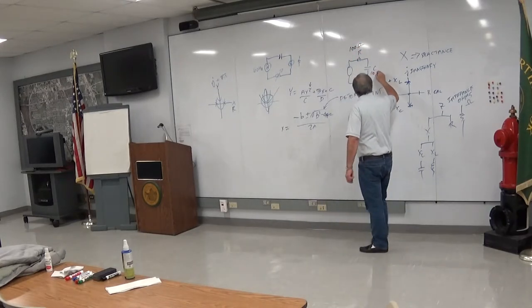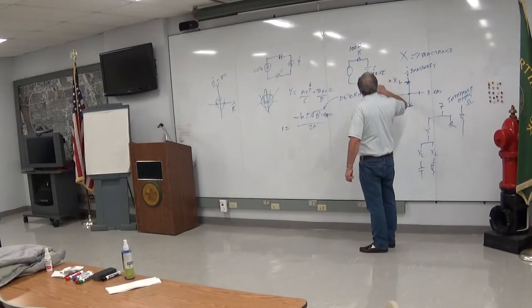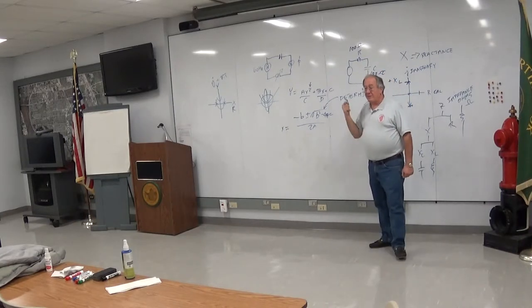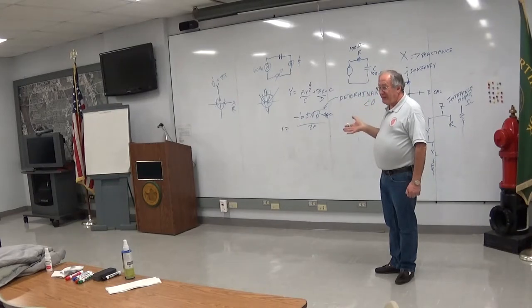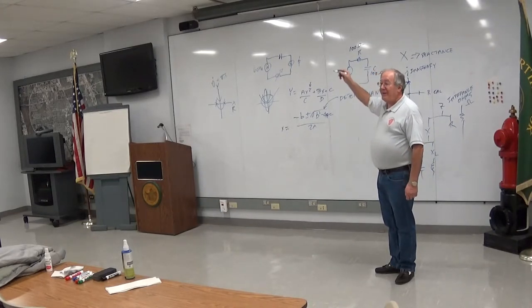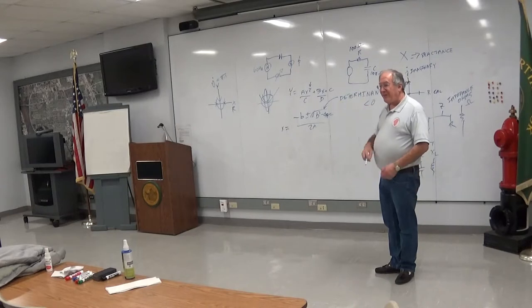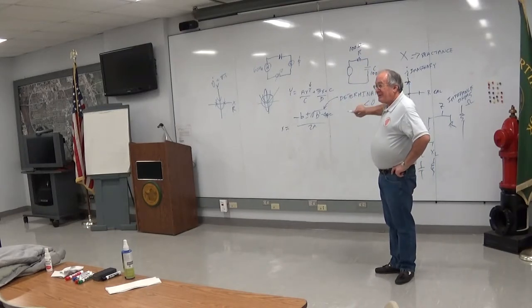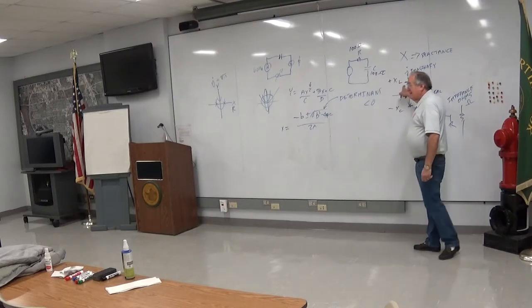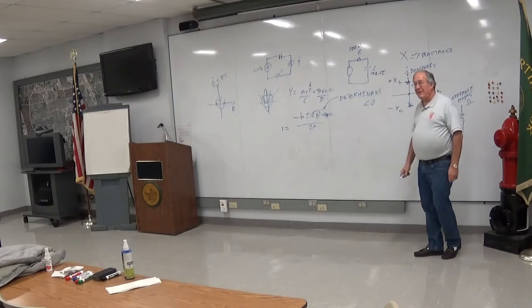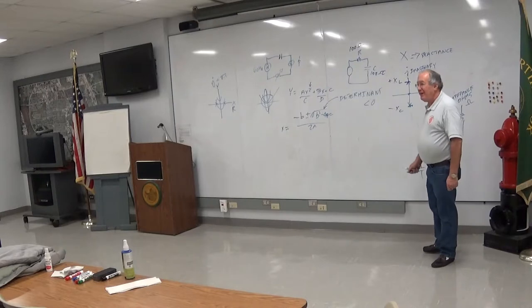And this thing's 100 ohms. And the 100 ohms in a capacitor depends on the frequency. But at the particular frequency, it happens to be that impedance. If the frequency goes up, the impedance goes down if it's a capacitor. If the frequency goes up, the impedance goes up if it's an inductor. Another reason for making this thing on the positive end is it goes up with frequency.